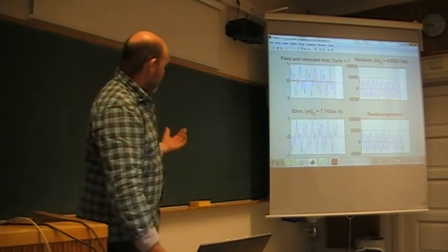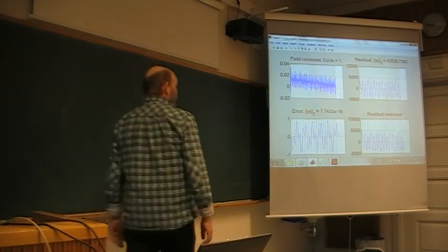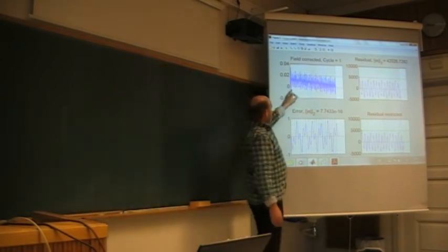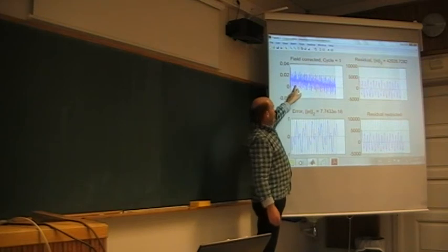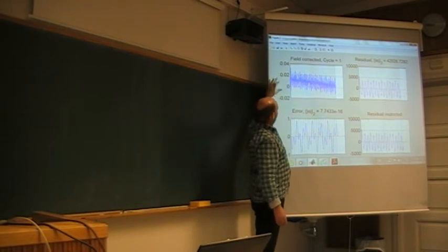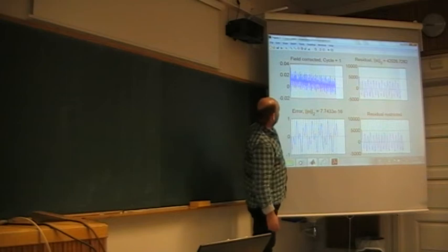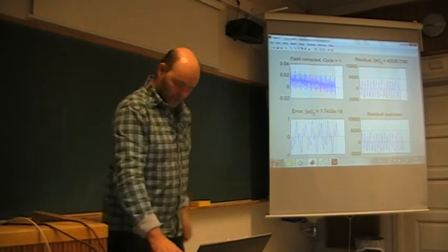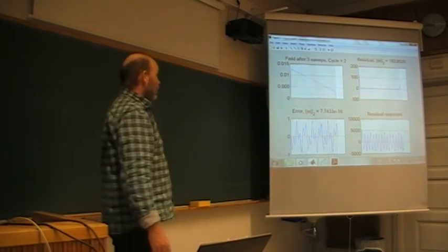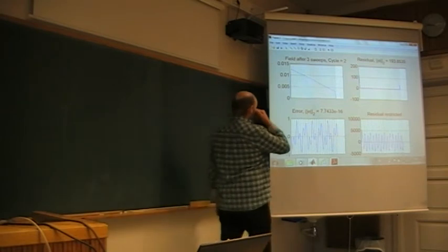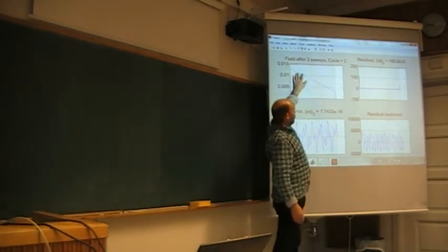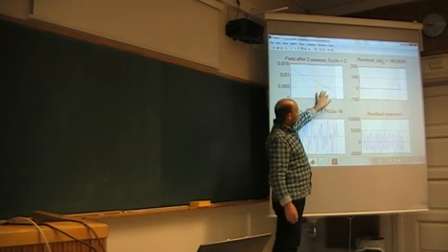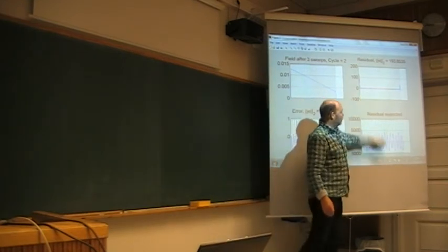And then we zoom in. Now I have this initial field, or original field, the fine mesh solution. And look at the scale, it's getting quite small. It was 1, but now it's only a few percent left. And now we do the same. Iterate 3 times. After 3 sweeps or 3 relaxations, we really get rid of all the noise, no problem. And now calculating the residual.